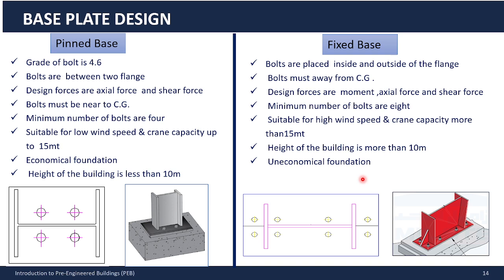The base plates connect the column to the foundation. There are two types. A pinned base uses bolts between the flanges and resists axial and shear force only. It requires a minimum of 4 bolts and suits low wind and crane loads in buildings under 10 meters height.